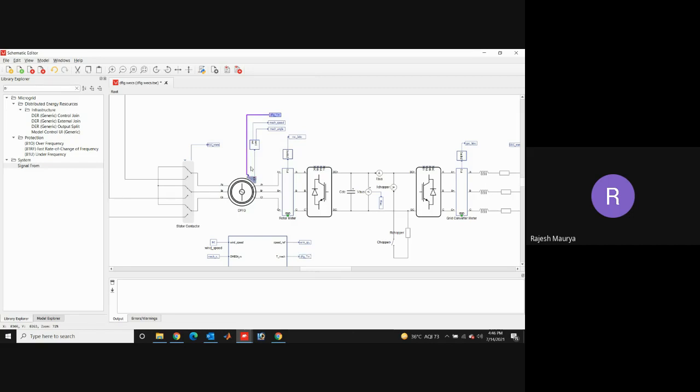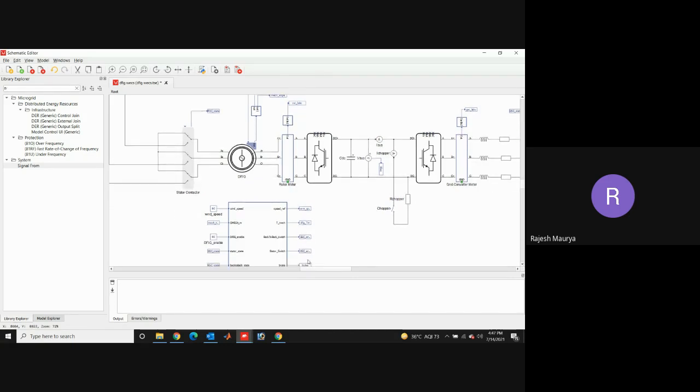You can directly send the signal also, but we make the circuit proper. That's why I've taken this. Sir, From tag? Yeah, we have taken From tag. Here it is Goto. We now require a From. Okay. So we have utilized this signal. Now we need to utilize these two. These two will be utilized for the measurement part, the speed reference and the angle for the measurement.